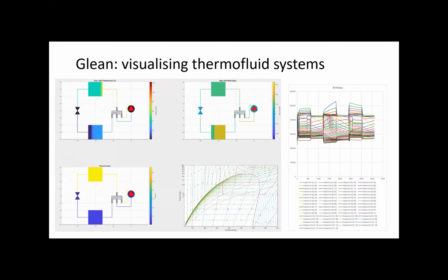So this is a heat pump system where you can do both heating and cooling in your house using the same system. In the cooling case, the compressor sends it to the condenser where it's cooled down, expanded, and then you have cold air inside your house. But you can also flip this valve such that the output of the compressor goes first into your house. So the hot from the compressor you can use inside your house to create heating, then send it back outside to do the cooling. So in the winters, you can use it for heating, and in the summers for cooling.